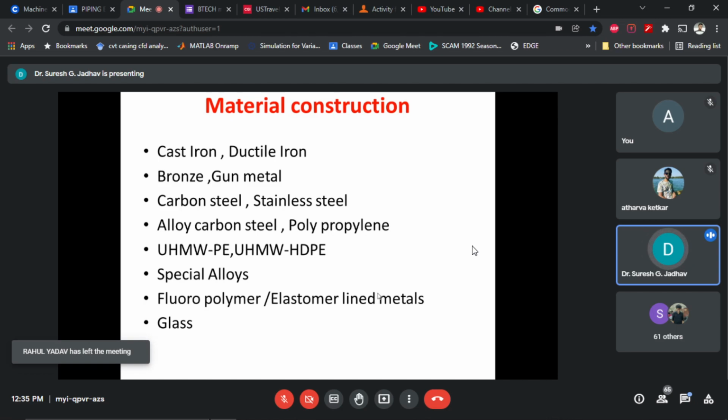These valves are used in different environments, so we have to consider them in process industries. It is for the piping engineer to select the material in consultation with the process engineer to suit the process fluid. The environment in which the valves are installed is also to be considered for the selection of material of construction.